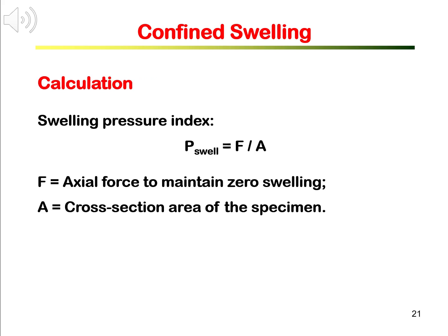As we mentioned before, the confined swelling test is to determine the swelling pressure index, which is the limiting stress to stop rock from swelling.